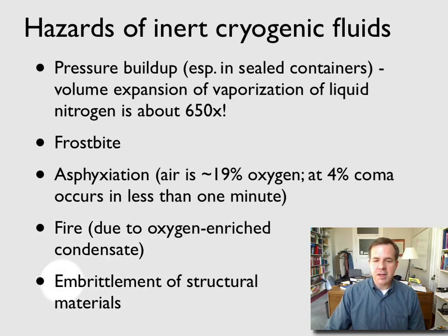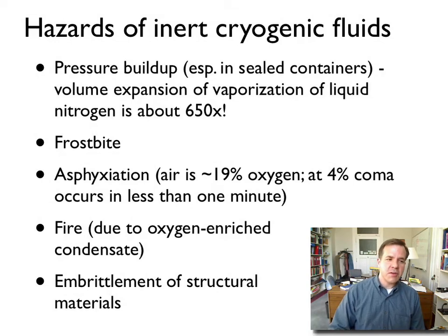And finally, if cryogenic fluids are poured onto or incident on structural materials, including many metals or actually in particular many polymers, that can cause them to become brittle and therefore fail, and that poses a risk as well.